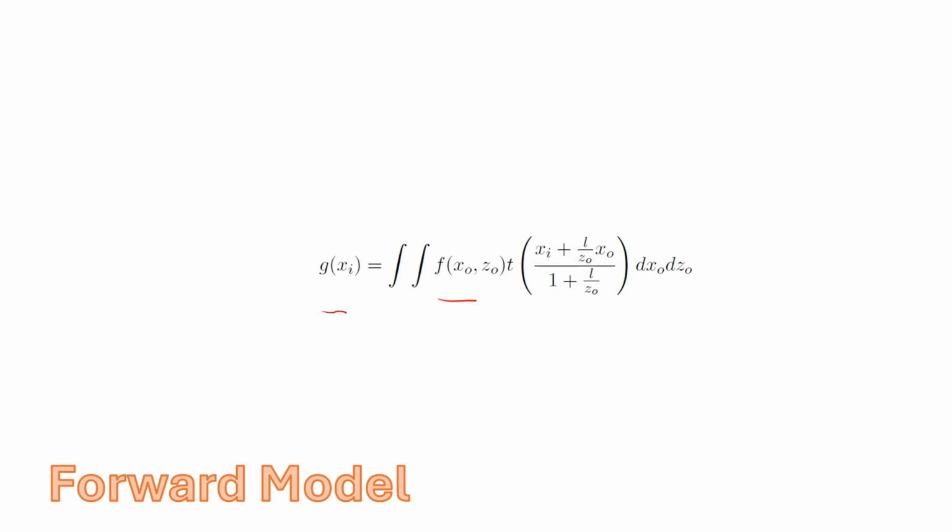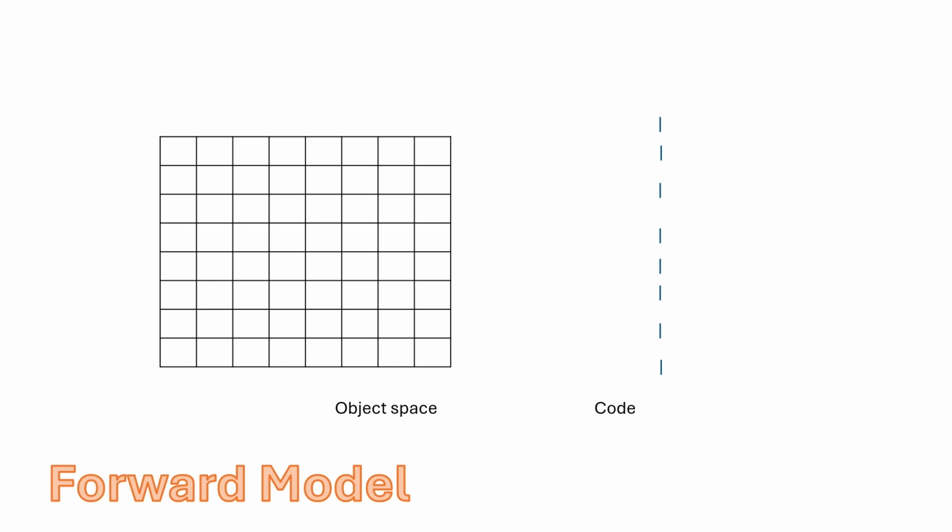We're labeling the longitudinal direction Z, and so we have this scaled version of the code according to the same models we used in coded aperture imaging for reconstruction, but now we're assuming we're reconstructing as a function of transverse direction and range. So if we think of our object space and a detector element here, going through the code, we have some visibility. And so if through the code these regions are visible, then they're coded with something proportional to the area that we see from that region onto the code. And we do that through each one of the coding elements, and we can develop a forward model.